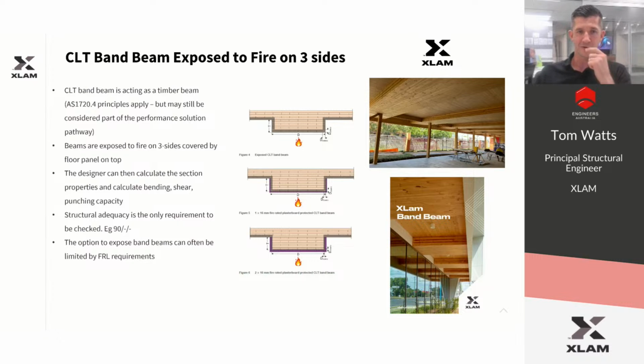So I guess it's probably worth pointing out that when architects and different designers want to use that system, there's often a desire to expose the band beam, or expose as much of the timber as possible. But when you're looking at these char depths at certain spans and fire resistance levels, it's the char of that system that is going to limit how much of that can be exposed and when encapsulation is going to be needed.